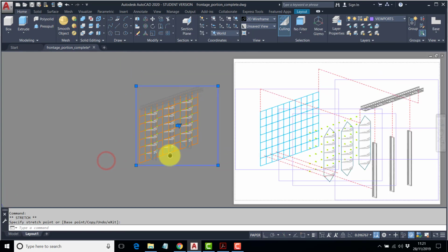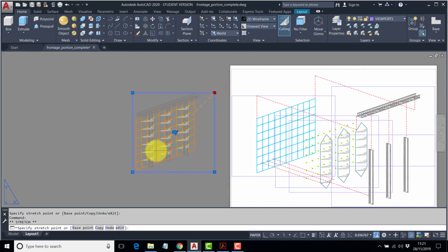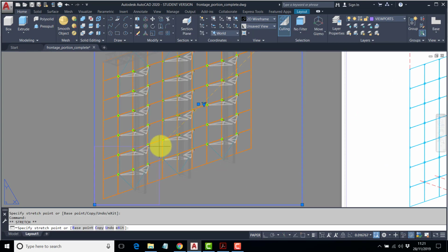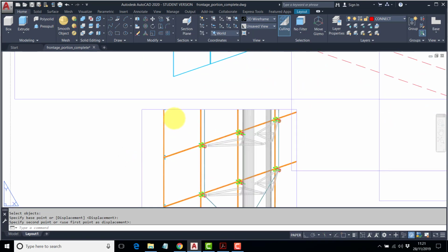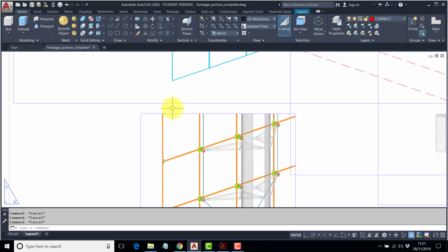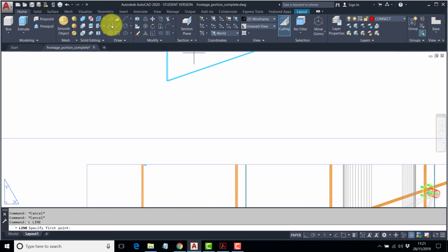Okay, but I just don't want to see the whole thing. So let's say we want to show just two trusses. Okay, and I'm looking for a space on the drawing for that. Okay, plenty of space down here. Okay, maybe I could line these up. It's very easy to do. Just draw a line, put O snaps on and ortho on. Just draw a line from the corner.